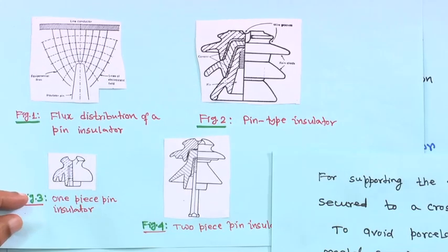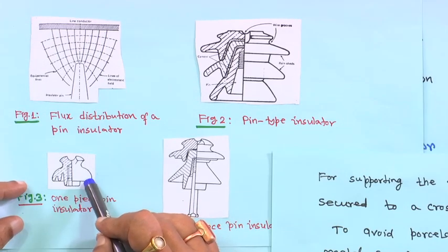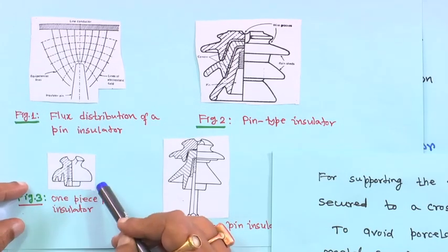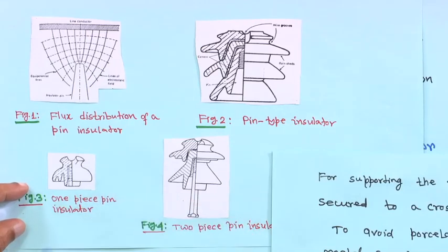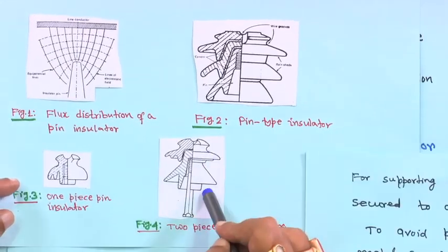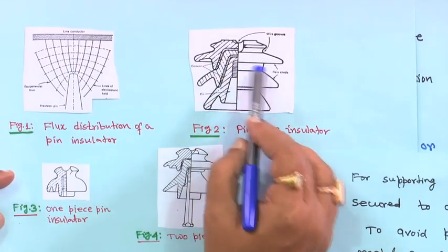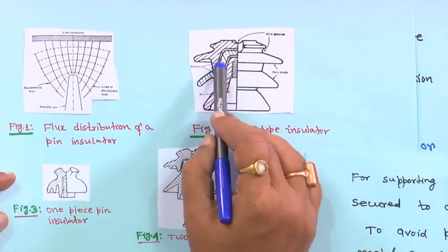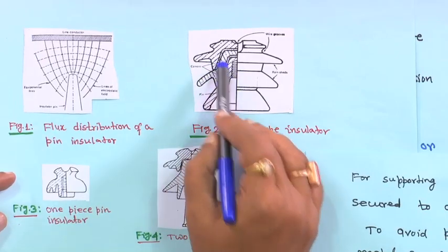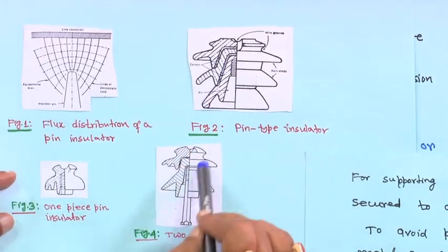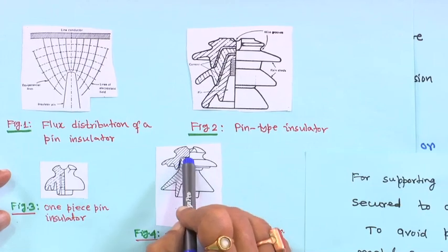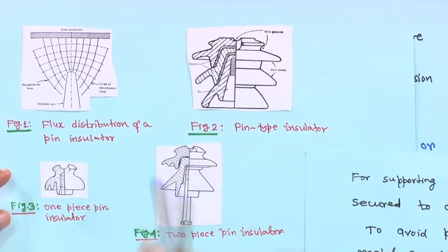Generally the thumb rule is that 1 piece means in general 11 kV, then 2 piece means 22 kV, 3 piece means 33 kV, like that. So, this is 2 piece, but the philosophy remains the same everywhere. If it is a 3 piece, then you will see two cemented joints here, but if it is a single one, then only one cemented joint is there, right.